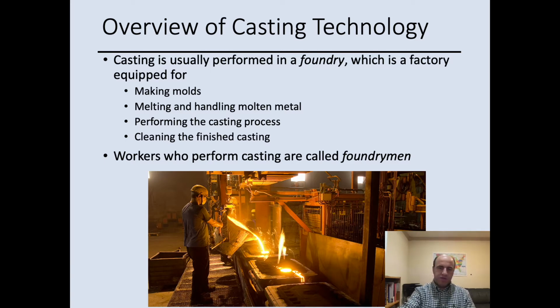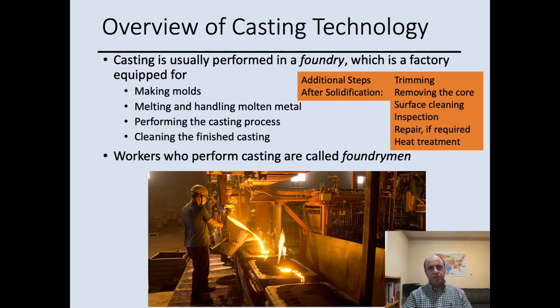And the process has several steps. Heating the metal. The heating of the metal is done by a furnace, which heats the metal to the molten temperature, and the heat that we need is the sum of three portions. One, a certain amount of heat is needed to raise the temperature to the melting point, and we have some energy, some heat, for fusion.